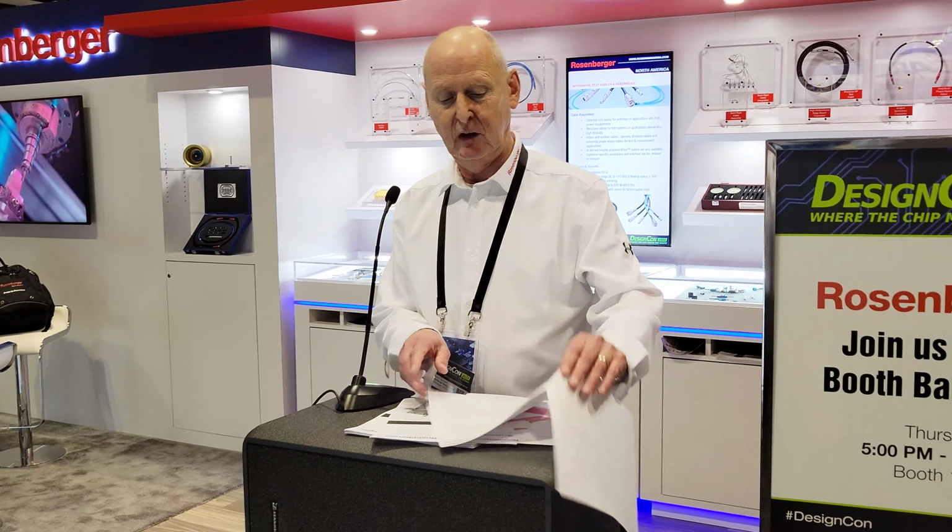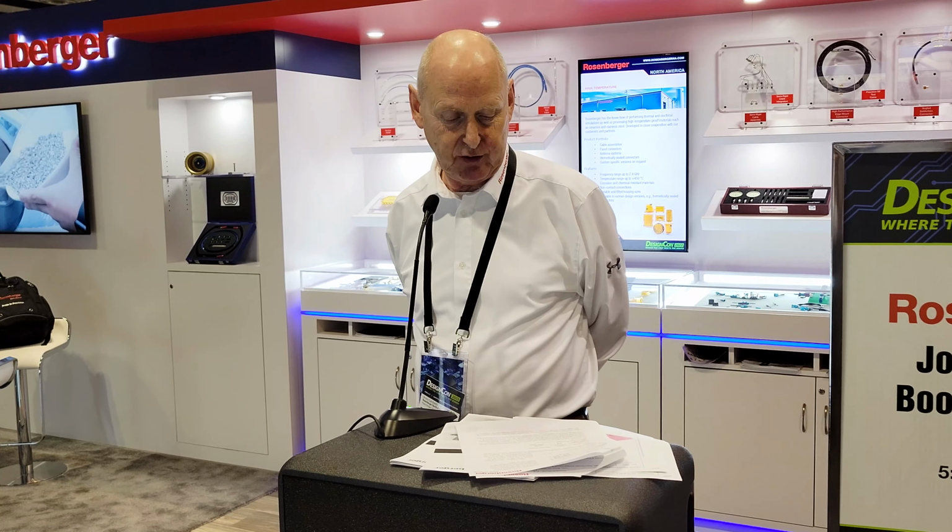Let's explore just for a moment what the PCB materials are and why they are important. In my application note, I have FR4 listed, an RO Duroid, which is trademarked Rogers, 5880, and then an RO 4350B. What's the dielectric constant? The dielectric constant is, of course, something that maps directly to the velocity of propagation, and the dissipation factor, while related to the dielectric constant, will be an indication of how lossy the microwave material is.